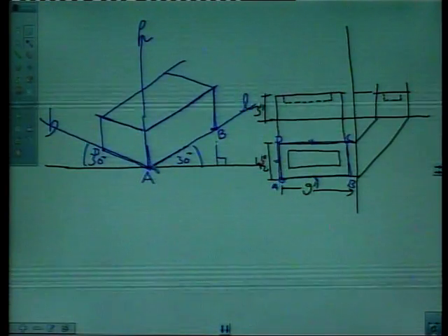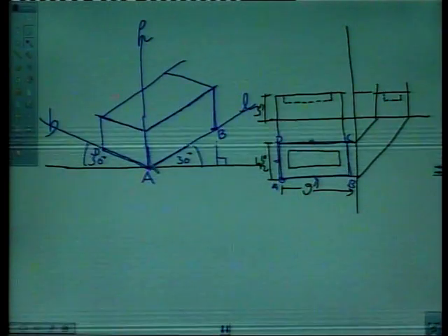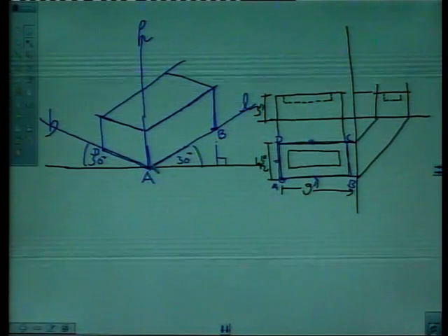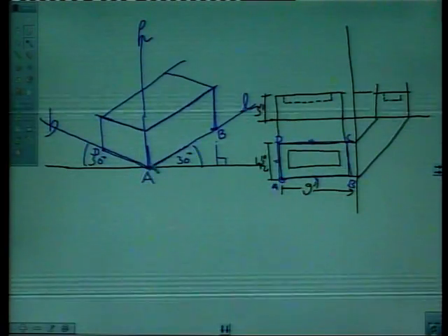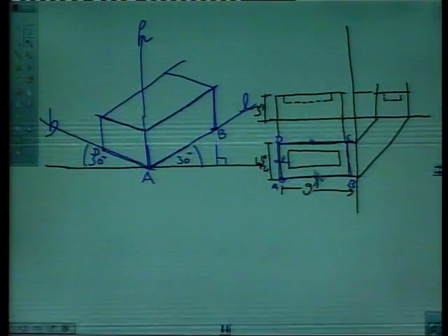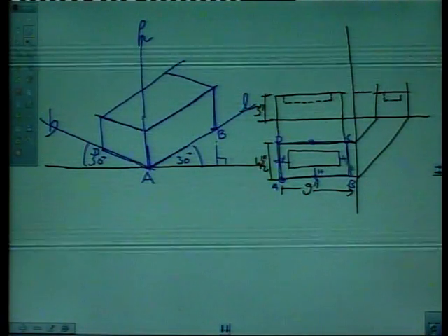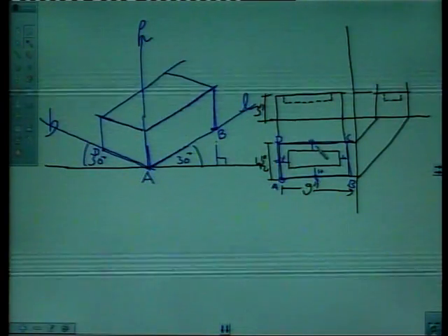So, this is 9 inch, this represents length, this represents breadth, and this represents top of the brick. So, how to draw frog, right? Say this is 1 inch, say 1 inch is from all sides, and rest is frog part, which is depressed part.